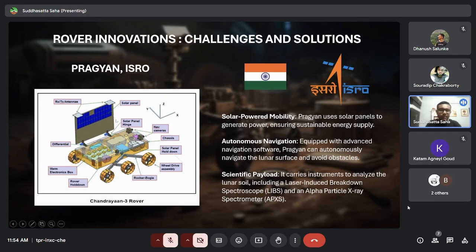It is designed in such a way that it can be folded to the other side. It's like opening a pencil box. You see, it opens up like this, pops up, and so the sunlight is incident and it is captured by this solar panel, and that powers our rover. And this is the differential, you can see midway, which is connecting these two sides of the rocker bogie. And this is the wheel assembly with the bearing and load bearing threads. These are the threads on the wheels which are responsible for the load bearing functions.